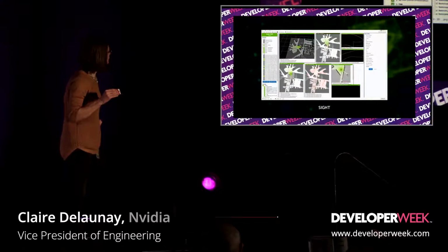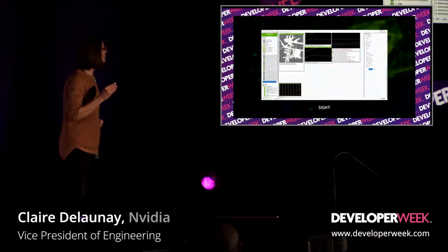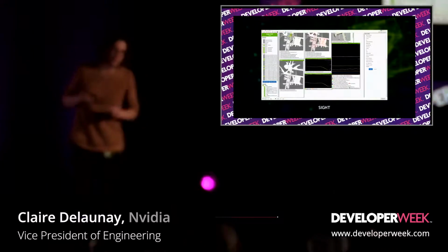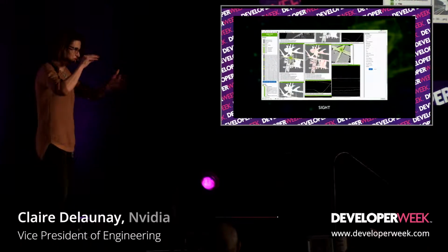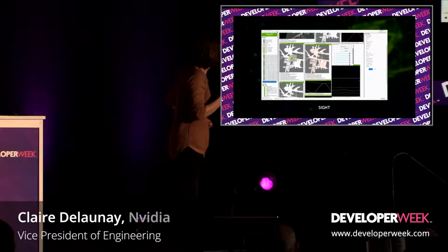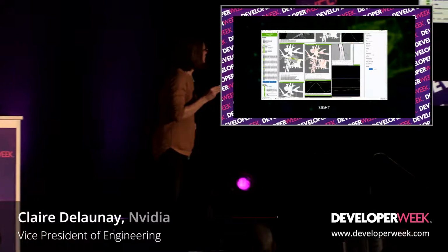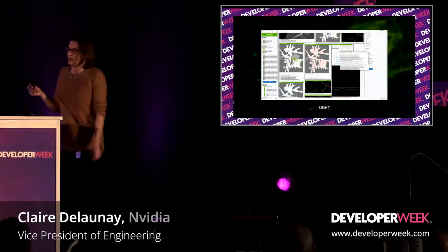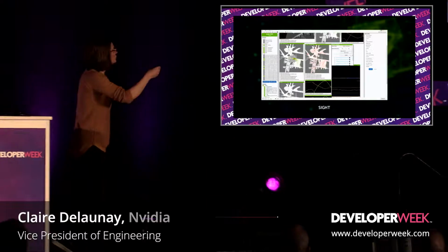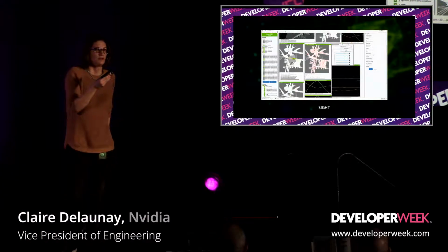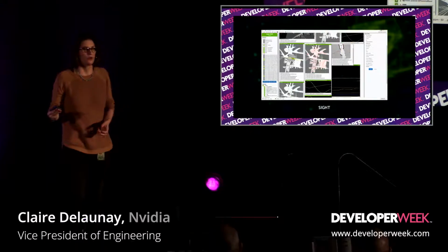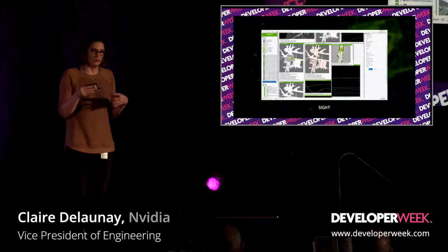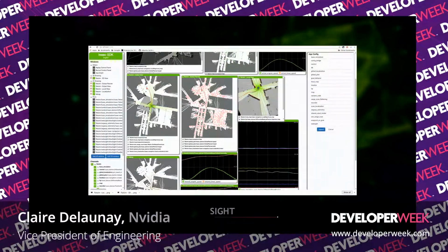We have a 3D visualization here that is more gamey and is very useful if you want to debug sensor placement and all of that, to make sure that you don't get your math wrong in your transforms. With this tool, you basically configure what you want to see, what is interesting to you. And again, it's very important to have these tools, because the dimensionality of data that you have on a robot is so big that if you cannot downscale it to something that fits on a screen, then it becomes extremely hard to debug. And so that's really what we try to do with Isaac.